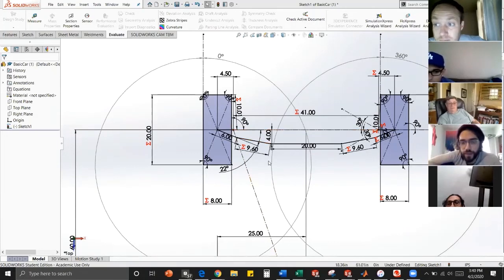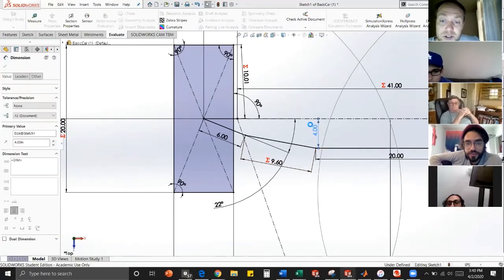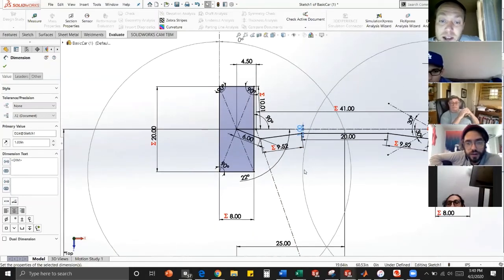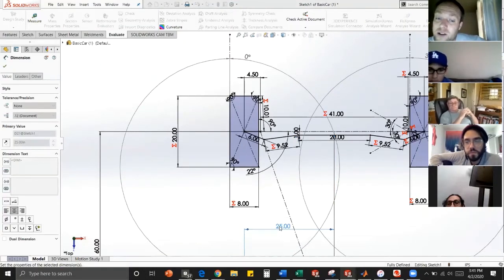Moving your rack forward is going to help in this case, because the point between the end of your rack and the steering arm, you're basically going to go farther away from going over center. So if this point goes up, your tie rod now goes here to here. That angle you can travel before, so make that 1 inch. Now you see the angle between your tie rod and the tie rod connecting point on the left and the steering axis has gotten bigger. That's good. You've also done good in that you're a little bit Ackerman excess, so that'll help your turning radius. If you're going to err, you want to be a little bit in the front. So let's see how far you can go.